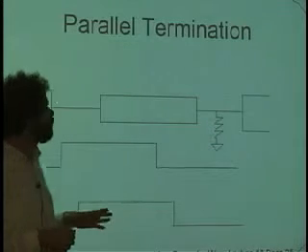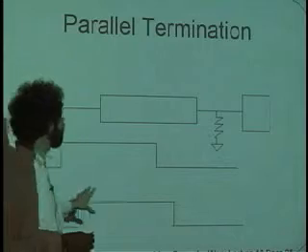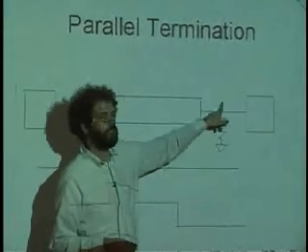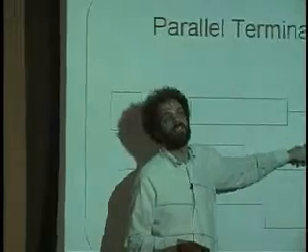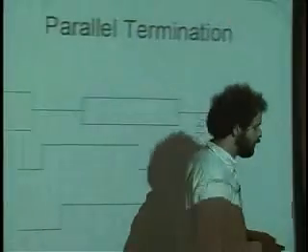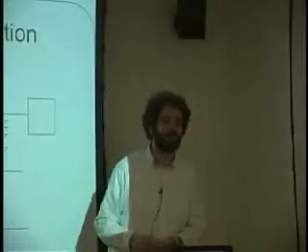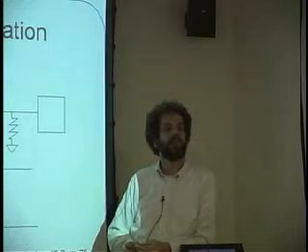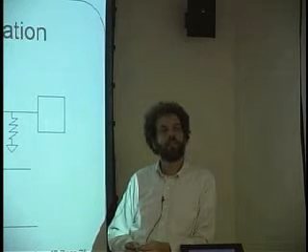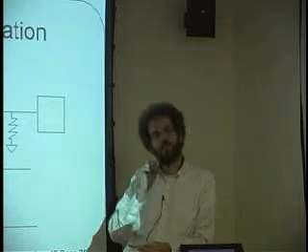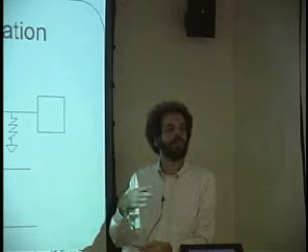And in computer design in general, particularly when you're dealing with high speed, you're going to discover that you're going to need to put terminators like this all of the time. And so modern computers have many more terminators than older ones have. And why should that be? Well, if I want to get around echo, let's say I'm in a room with a lot of echo, what do I do? I talk really slowly, because in between each syllable that I say, the echoes have time to die out, and so they don't end up clobbering the future things that I say.